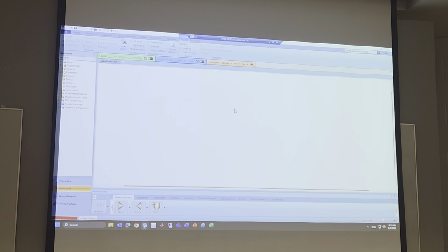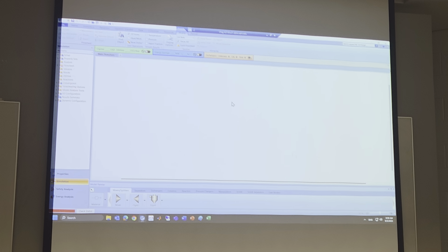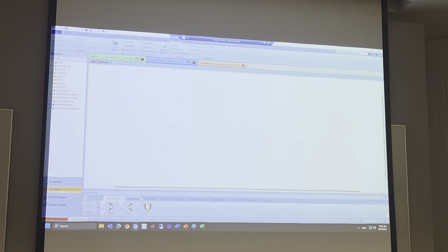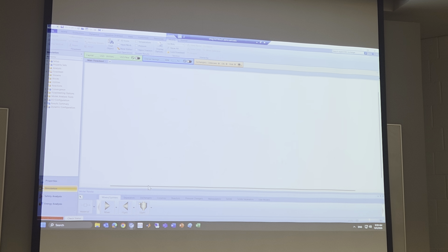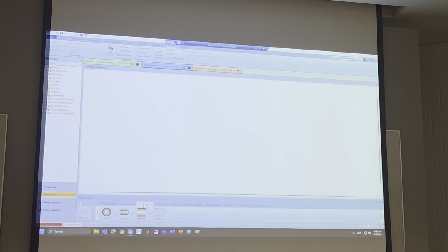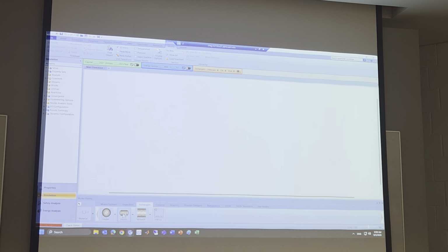Anyway, let's go. Process flow sheet. If you have a laptop, you can open the process flow sheet. Okay, we have a heater. If you go to exchangers, there is a heater, and the next one is the shell and tube type heat exchanger. Simply, it's a heat exchanger. So let's use a heat exchanger for the heater. We want to preheat our feed stream.